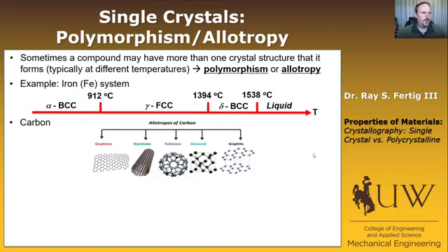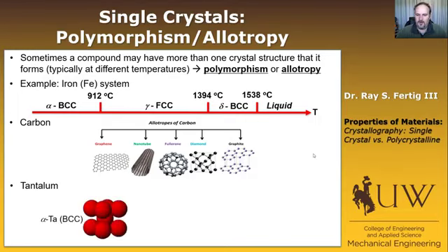Let me bring up one more, and that's tantalum. The reason I bring that up is because this is one that I've personally worked on a lot. Back when I was doing my PhD at Cornell, one of the projects in my group was focused on looking at the phase transformation of tantalum from its normal BCC phase, which is alpha. So I'm showing you a BCC alpha tantalum.